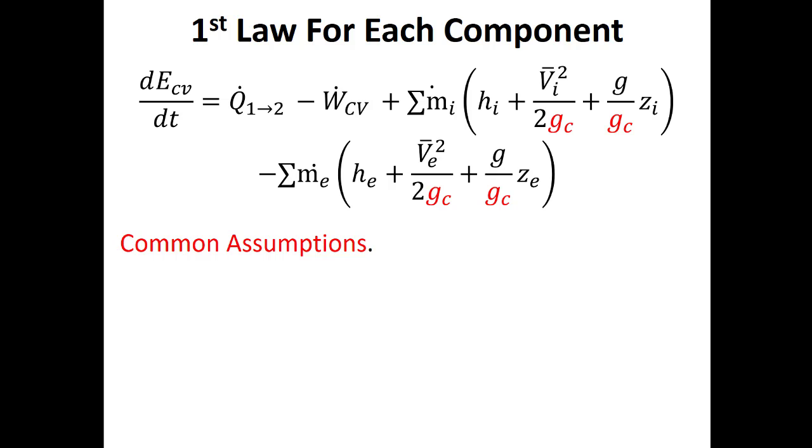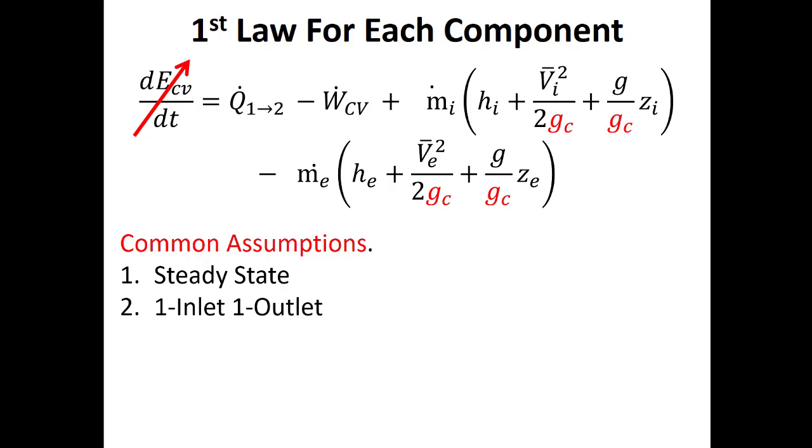This is thermodynamics class. So what we're going to do is we're going to use the first law of thermodynamics, right? These are open systems. So just like a Rankine cycle, just like a Brayton cycle, just like a turbojet, all of these processes are happening in a different component. So we'll have to look at each one of the components and we'll make some assumptions. In this class, we're always going to say that things happen at steady state. We're almost always going to say that things are one inlet and one outlet. The time where that's not true was a Rankine regeneration cycle, right? Or I guess if you have some heat exchangers, then you know what's going on the hot side and the cold side. But we'll often say one inlet and one outlet.